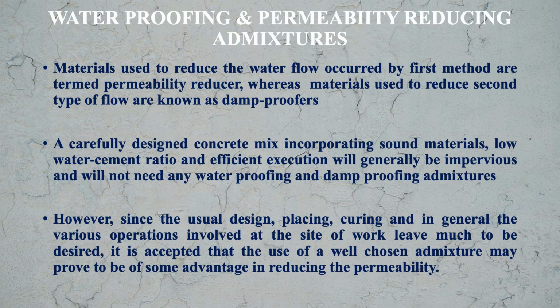What is the meaning? If we are having concrete which is made of sound material, we have used a low water cement ratio, and also efficient placing and compaction is done for the concreting work, then the concrete obtained will be a good quality concrete which will not require any waterproofing and damp proofing treatment.